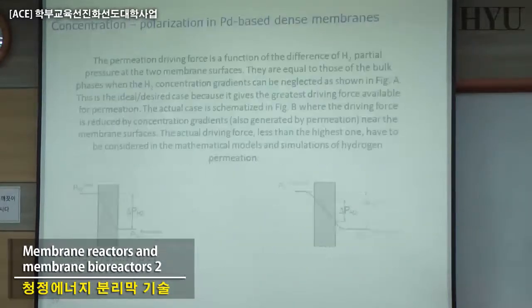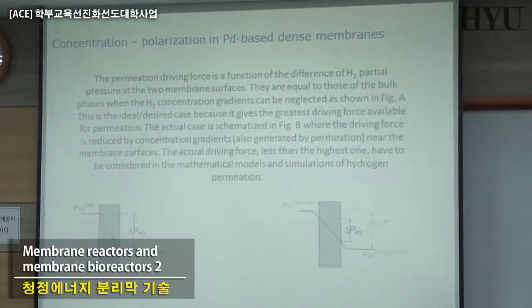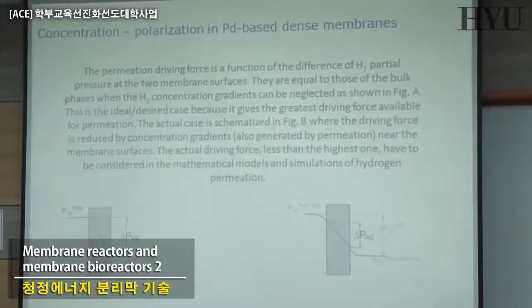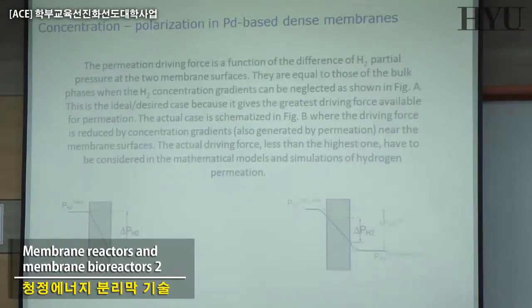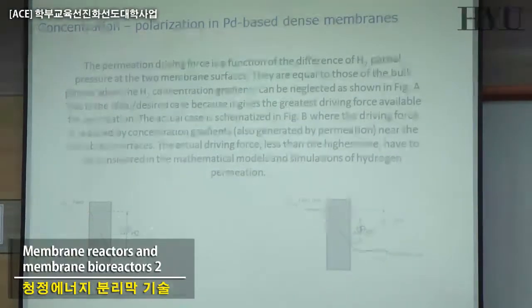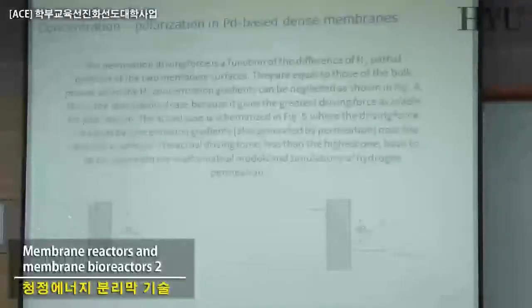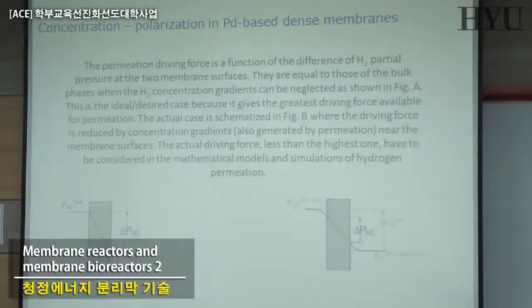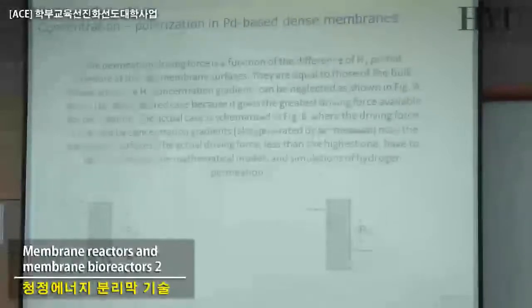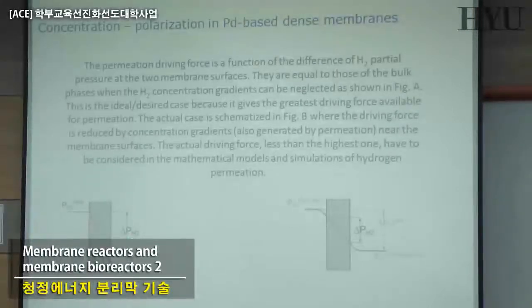This problem can be a little bit more complicated, and first of all, if you want to see what it means in terms of calculation, in terms of changing the driving force, this is the typical situation if there is no concentration polarization: we have a certain partial pressure of our component on the feed side, a certain concentration on the permeate side, and that difference between the feed and the permeate is the driving force, just the difference in concentration.